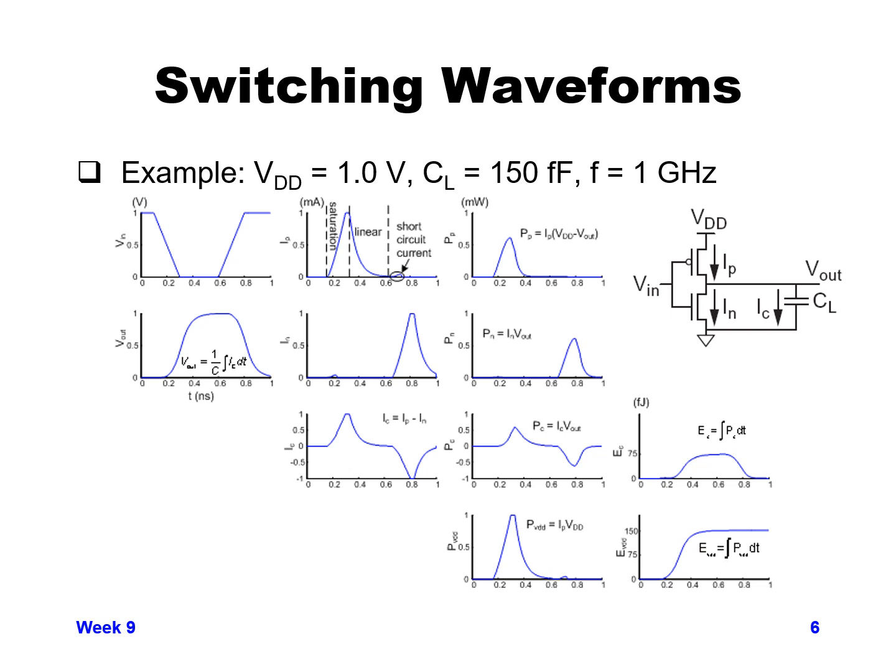So you consume all of your energy from the power supply in charging up the capacitor, and only half of that energy gets into the capacitor. Half of that got consumed by the PMOS device, and then you consume the rest of it when you discharge the capacitor. But the overall amount of energy that you pulled from the voltage supply happened when you initially charged the capacitor.